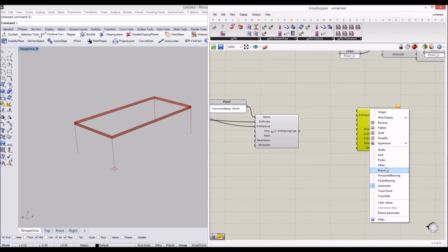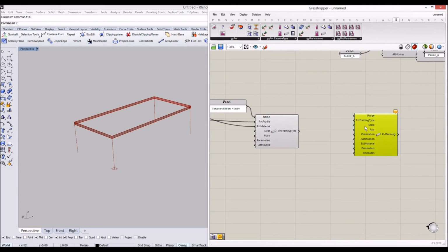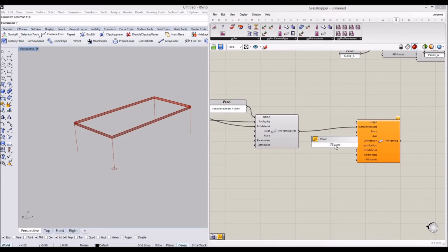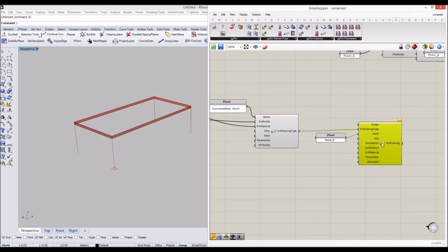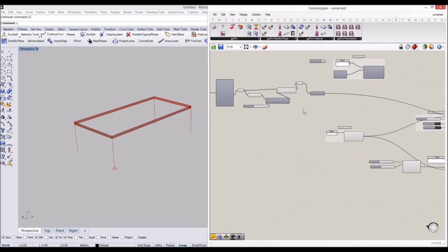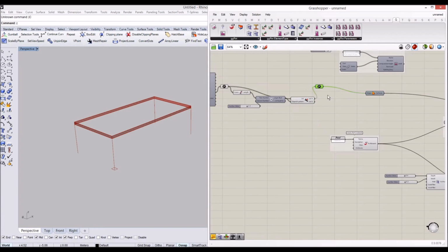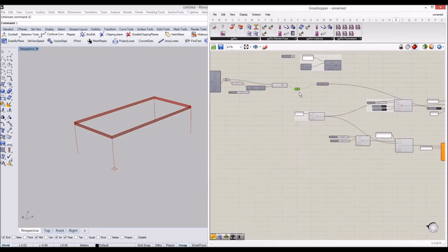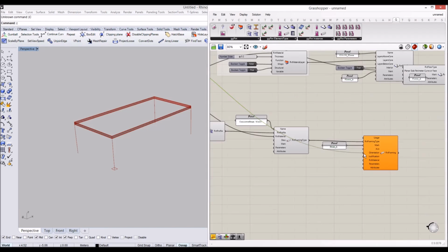At the moment, as default, it's automatic, but let's say it's going to be girder, that we can keep that information. And for the framing type, we'll use the type parameter that we connect in here. And for the type mark, I'm going to give Beam A as a type mark parameter. Okay, and you will use these axes, so that beam axis will be from the dispatch component. We extracted these lines, so we'll connect this one to axis.